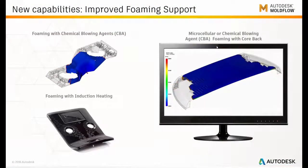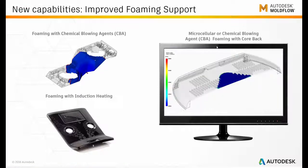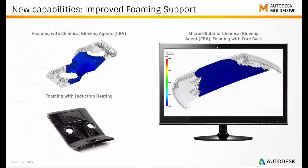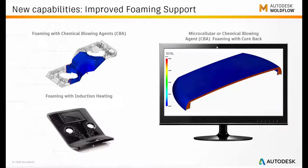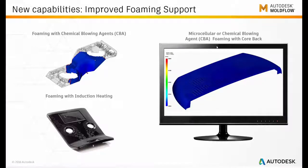We extended the foaming capabilities to not only support the MuCell capabilities we had in prior releases, but we also now support chemical blowing agents, as well as the ability to use a core back simulation. So once the foamed part is filled, move one of the cores back, create an under pressure in the interior of the part that promotes the foam growth and creates a very nicely foamed structure. We also added the ability to use induction heating with the foaming process.